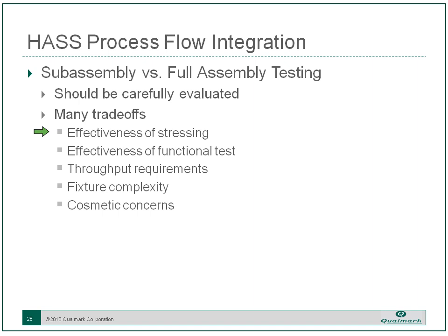Don't automatically assume that you're going to do it on the final unit, because one of the nice things is, if you don't do it on the final full-up unit, you don't have to worry so much about scratching things. And that, of course, as we all know, is a big no-no. And to be able to eliminate those cosmetic concerns by not putting on the final case until it's ready to go in the box, you've eliminated yourself some headaches. And the fixture complexity can go either way, depending on how hard it is to fixture your full-up assembly versus how hard it is to fixture those sub-assemblies. That's something to work into your decision-making.